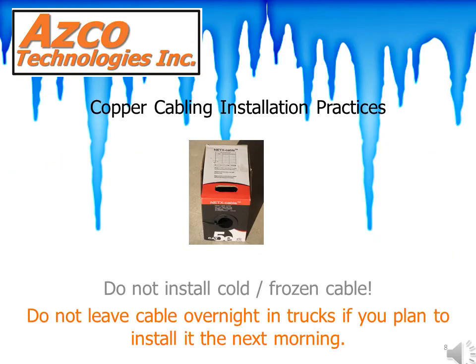Do not install cold or frozen cables. Do not leave cables that may freeze in trucks overnight if you plan to install it the next morning. Cold or frozen cables are more difficult to pull, but can be very easily damaged when pulling into place.